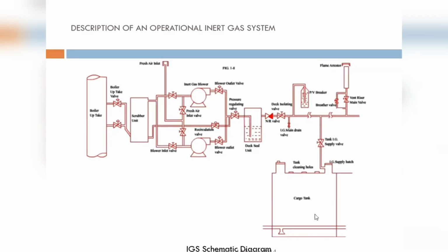In the cargo tank, the vapors have to be removed from the airspace, and the inert gas which is there has to be removed. Only then can the oil occupy the space, otherwise it will rupture the tank, as the pressure will start increasing. So while loading, these vapors come out from here and go out through the mast riser to the atmosphere. That is the venting arrangement; the IG main line is also used for venting the inert gas while loading the cargo tank.